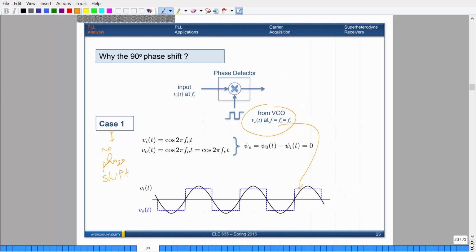So what happens when you multiply these two things together? Well, the square wave just oscillates between -1 and 1, right? For any points that are -1, you multiply those points with whatever sinusoid you get out. When you multiply two negatives together, you get a positive, right? So between here and here, this rectifies it so it goes up like that. Same thing over here. Whenever the outputs are both negative, you rectify them so that they're both positive.